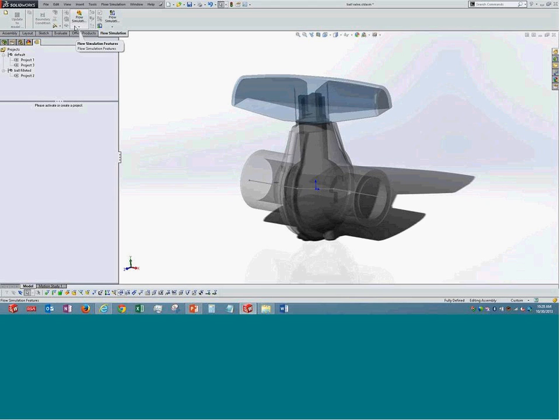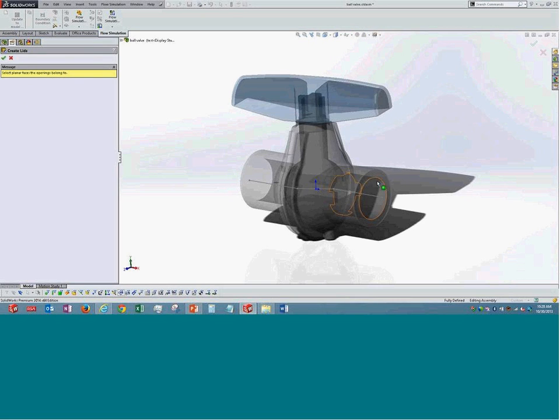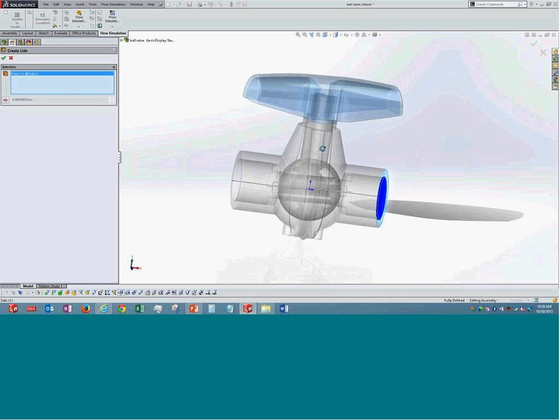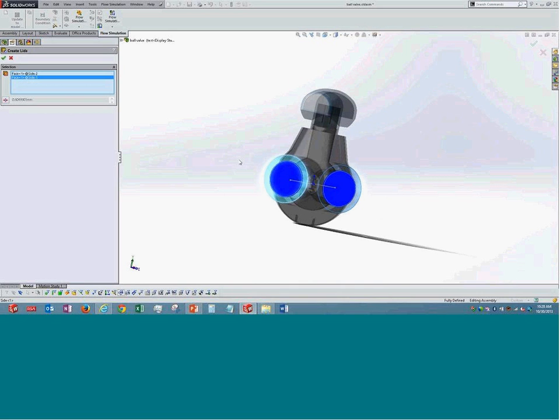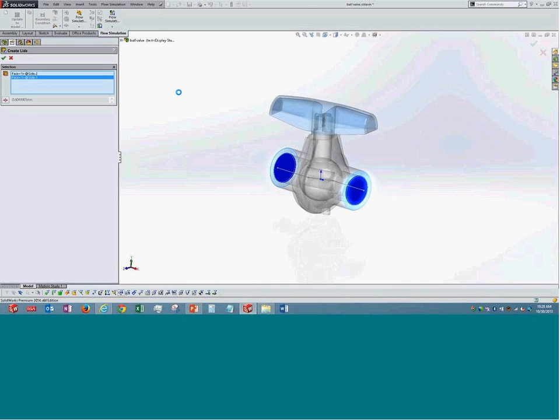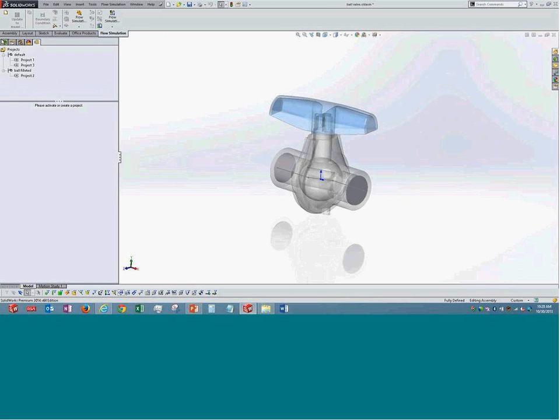Here it is more CFD oriented and integrated into the SolidWorks CAD module, and it creates those lids automatically. So from an understanding perspective, we just scroll the model, find any such gaps and fill them with lids. These could be places where we are giving some kind of input, that is air is coming inside or going outside, or it could be a case wherein you need to close these particular entities, or I would say holes.